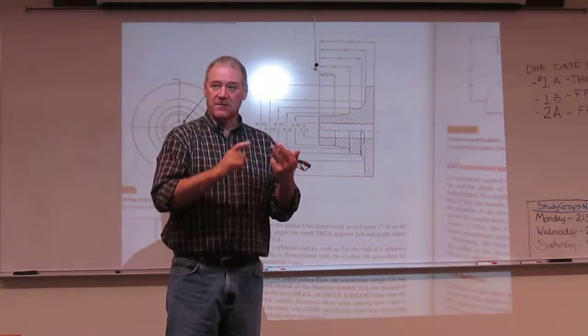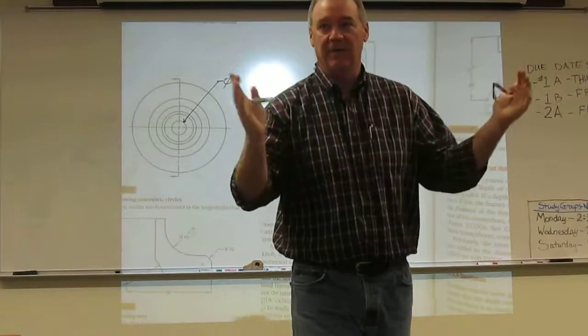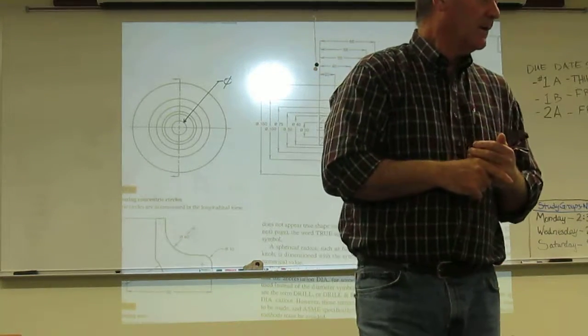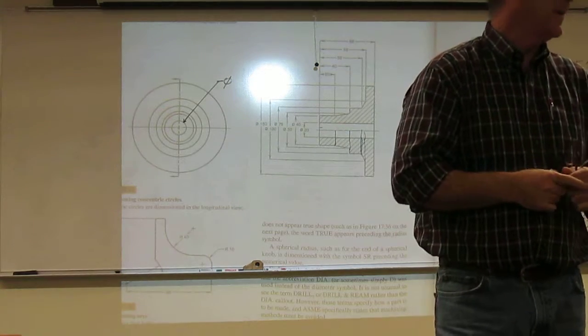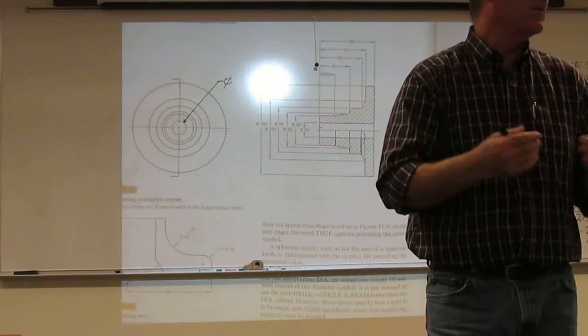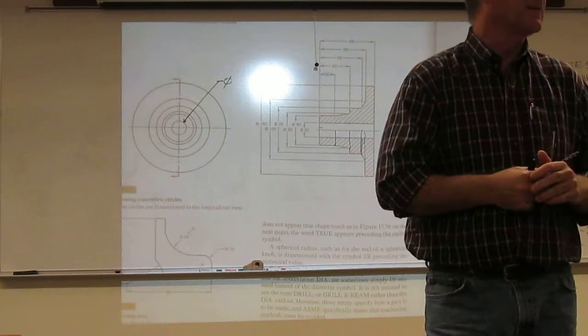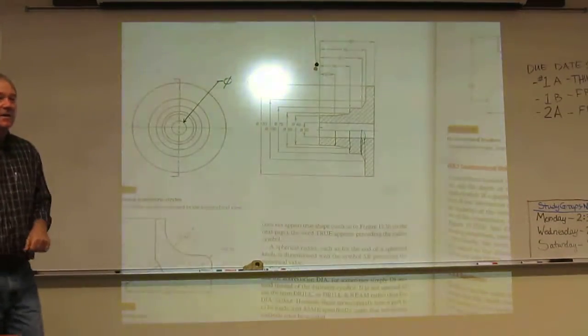So general consensus, whenever you have a cylinder, always locate them in the circular view. Just locate them. Positive cylinder, put the size dimension in the rectangular view. Negative cylinder, put your size dimension in the circular view, unless you show it in section. Then do it like a positive cylinder. That's a general consensus that'll handle 90% of all of your cylinders.